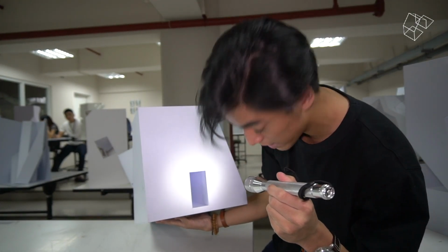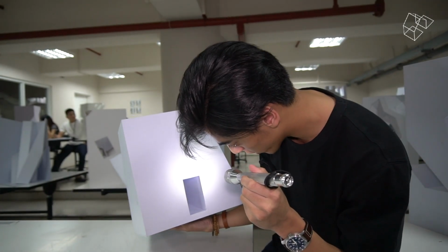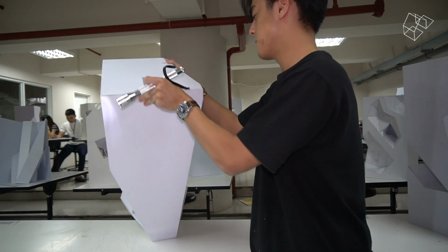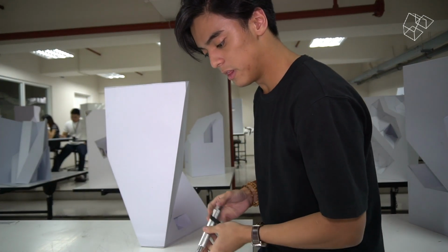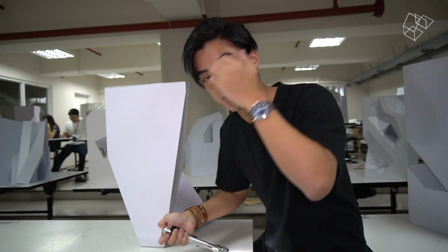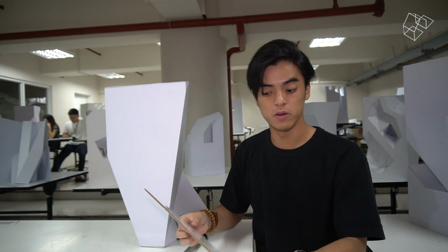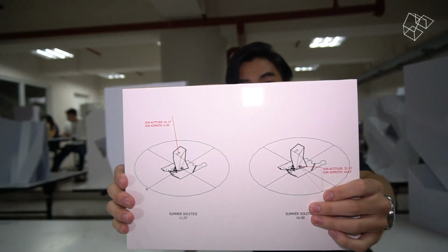The light touches the end of the hole properly. The walls, given that it's a narrow hole, do not hold too much light. The sun altitude for the summer solstice solar noon is actually 81.7 degrees, and its azimuth with respect to the north is 0.38 degrees, if you see it in the diagram.